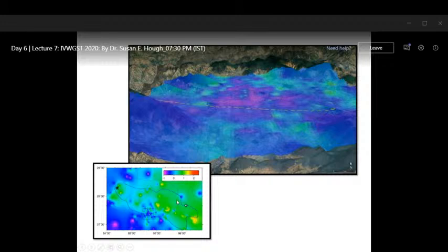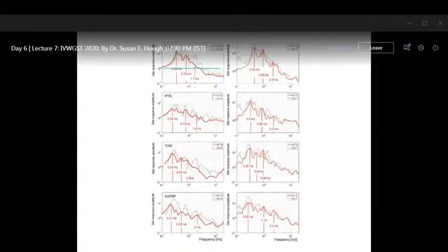If you come into the Kathmandu Valley and break that over topography, what you can see is purple. In the middle of the Kathmandu Valley, the intensities were lower than expected, not amplified, not like the simple models predict. So if you look at the available accelerometer data that were installed by a Japanese team working in collaboration with a local Nepali team, you can look at the shaking at sediment sites in the valley compared to a reference site on hard rock.